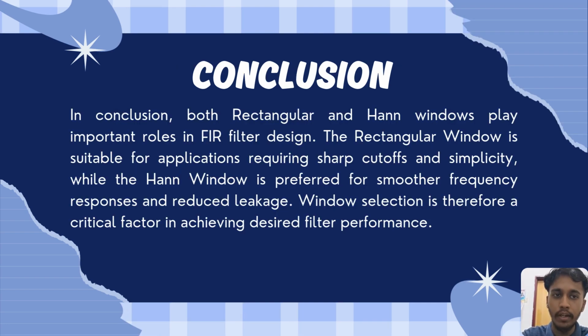So for the conclusion, we can conclude that both the rectangular and Hann windows are really important tools when we are designing FIR filters. It's not necessarily about one being better than another. It's more about choosing the right tool for the specific job we are doing. If we need a filter that has a very sharp cutoff and we need it to be as simple as possible to build, the rectangular window is a great choice.